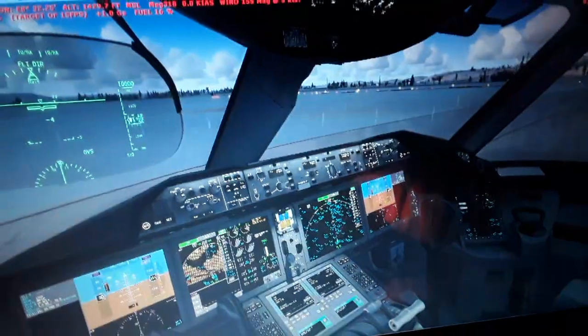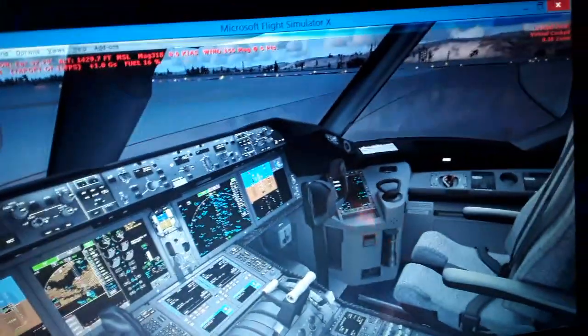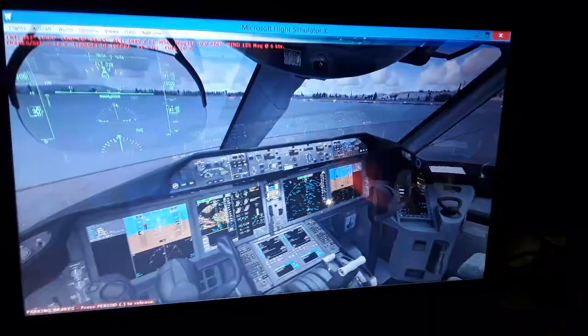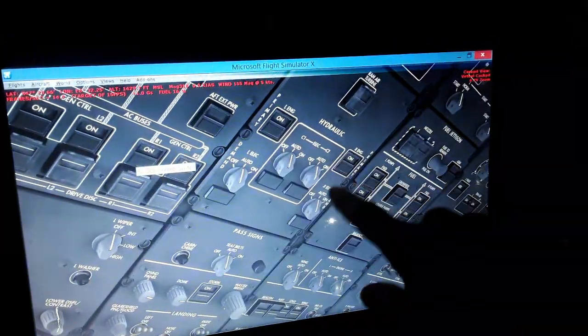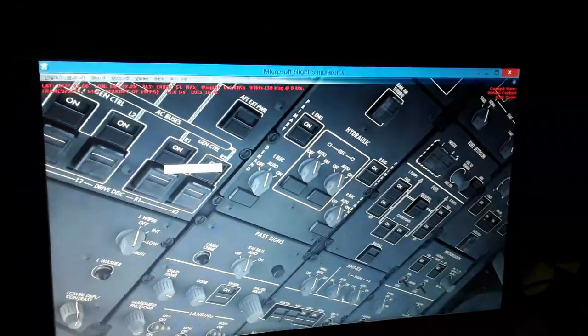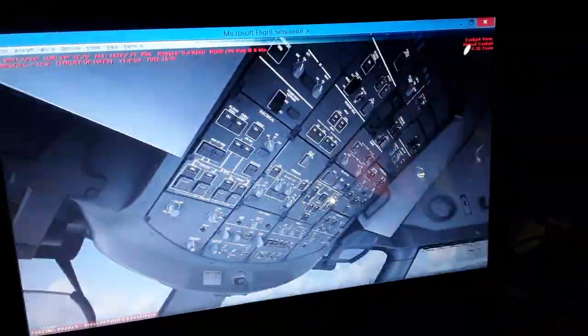The outside view. You can see we use the horizontal stabilizer to balance the aircraft inside as we fly, to relieve the pressure from the yoke. And also we have the auto trim, since this is a fly-by-wire aircraft. So we have a failure of the L2 and R2 hydraulic systems that affects the L2 and R2 horizontal stabilizer. Over here we have the hydraulic pumps. You can see the left engine and right engine and electric C1 and C2. I'm gonna show you the overhead panel systems later.